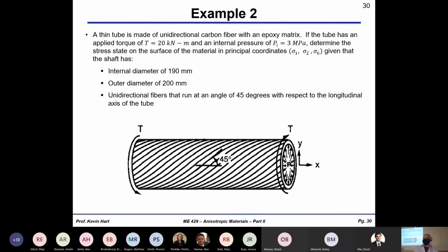We've been doing a lot of math, so I wanted to bring it back to some practical engineering problem. What manufacturing process was likely used to make this tube? What did you say? Totally RTM. Incorrect. Who's got it? Filament winding. The right one. Riley says pultrusion. Could also be pultrusion, but with this 45-degree orientation, highly unlikely.